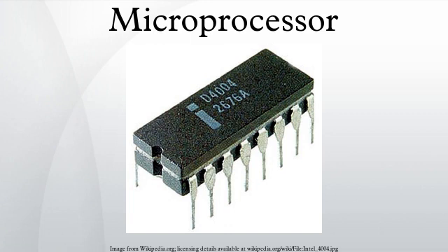The two chips are programmed as a unit using a single integrated instruction set. Though the 8087 coprocessor is interfaced to the CPU through I/O ports in the CPU's address space, this is transparent to the program, which does not need to know about or access these I/O ports directly. The program accesses the coprocessor and its registers through normal instruction opcodes.